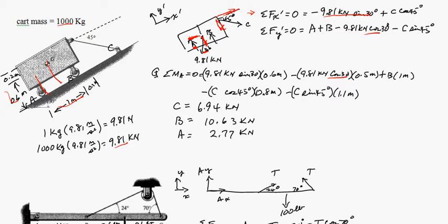The x component is going to be times the y distance, so that's from here to here, so that's 0.8. And then the y component is going to be times the x distance, which is 1.1. And then you solve the algebra.